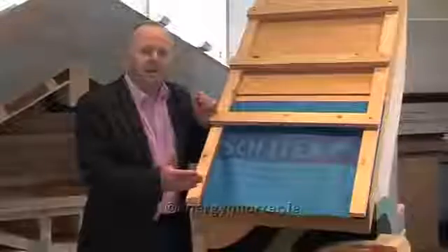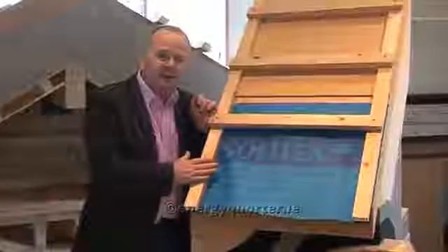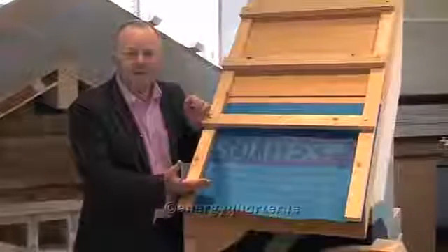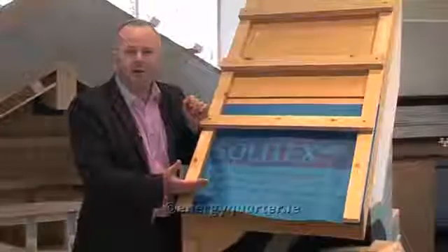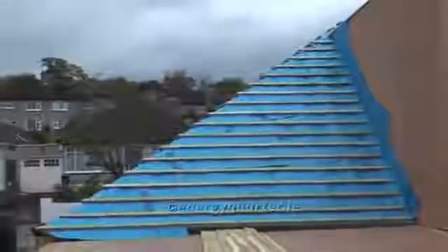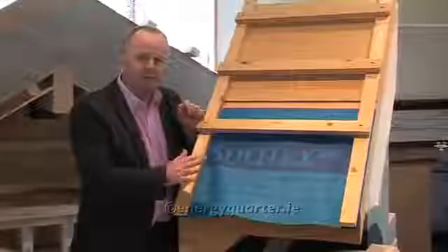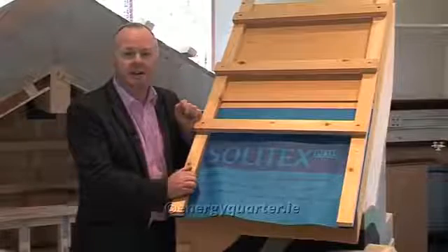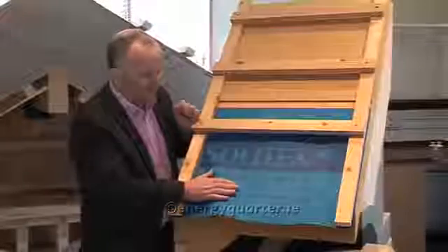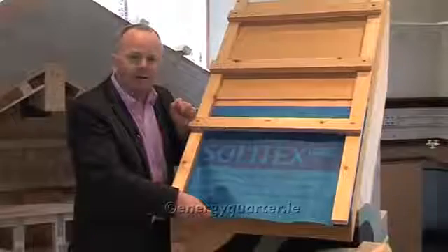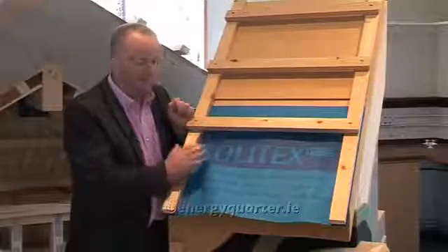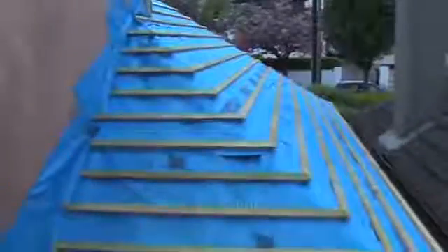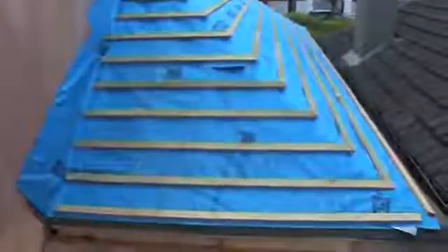Having looked at the airtightness membrane on the inside of the building, let's imagine now we're on the outside of the house, and now we're thinking about wind tightness as opposed to air tightness. And wind tightness is very important in climates like Ireland and the UK, because we have quite high wind speeds. And if you have a lot of cold air blowing across the insulation, it can actually reduce the insulation value of that. So here we use a special membrane, and when properly fitted like this, it produces a very nice wind tight layer, and therefore greatly reduces the heat demand of the project.